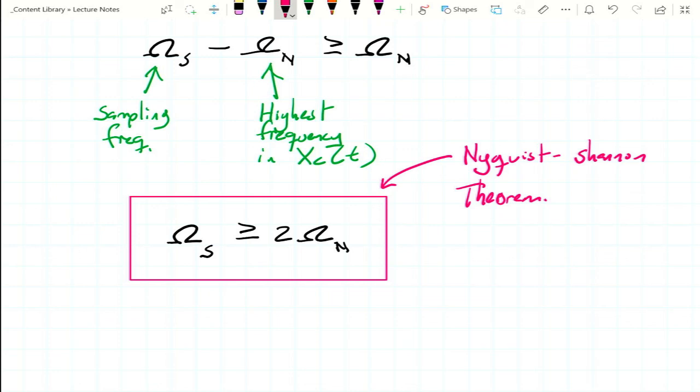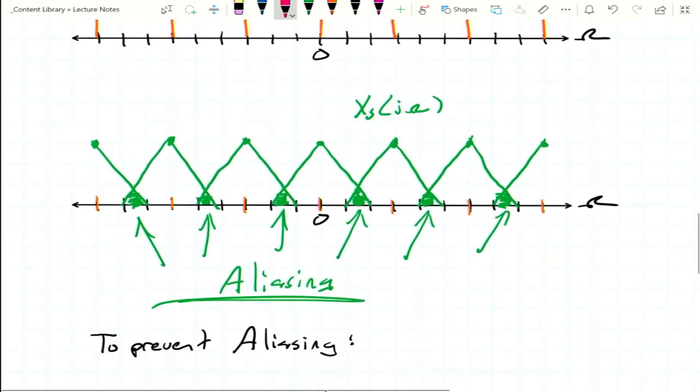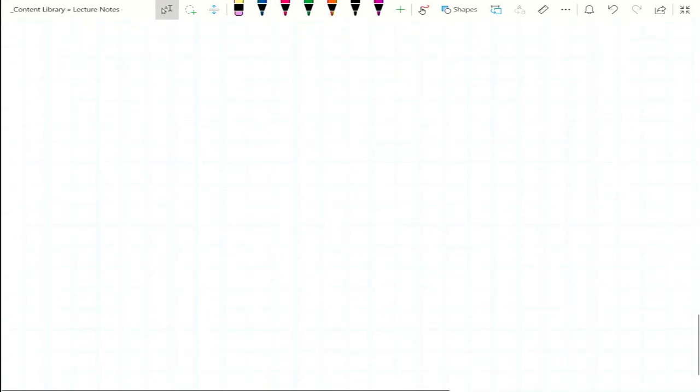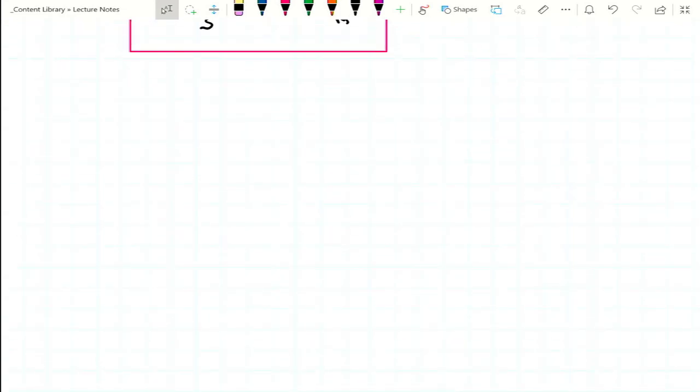Let's dig into that just a little bit more and take a look at how that distortion matters to us, because this is still kind of a theoretical construct. We can draw the graph and see that stuff gets jacked up, but how does that lead us to actual distortion in our signal? To get there, first we're going to draw our diagram, our model for our system. We're continuing to refine our model for that ideal continuous to discrete converter.